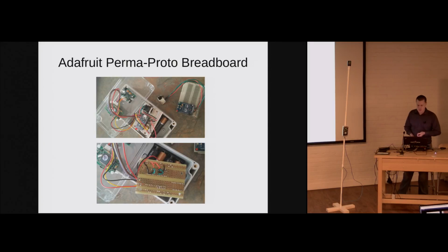It just has the typical 8 pins that you would find on a normal Ethernet connection. And I'm only using 4 of those. I just need power, ground, RX, TX. And I soldered wire to those pins and then ran those into the radio. And so at the top of the pole is the transmitter radio. And that just has the 4 pins that I need connected right to that Ethernet port. The Ethernet cable runs through it, comes out into the box.